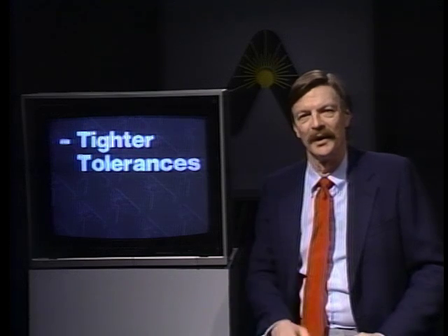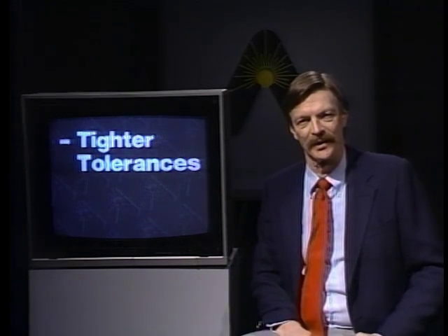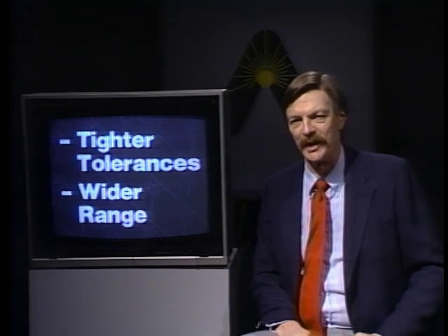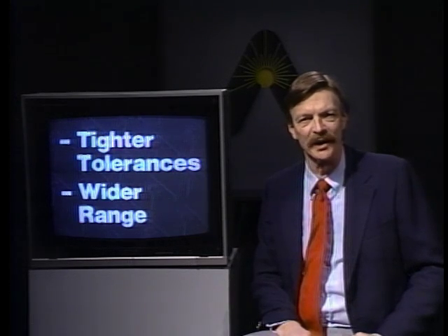What are the advantages of the multiple component automatic loop with its greater cost, greater number of parts, and therefore greater opportunity for failure? The loop can operate within tighter tolerances. Pressure can also be controlled over a wider range, from a lower minimum controlled flow to a higher rated capacity.